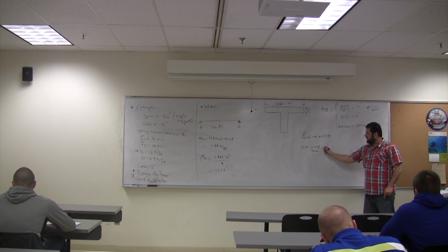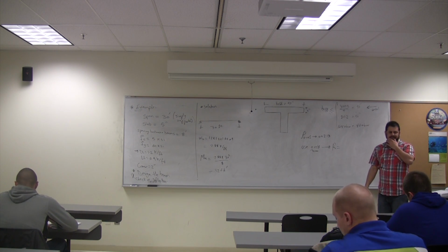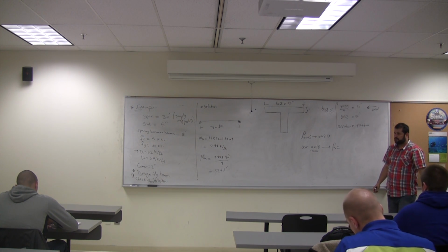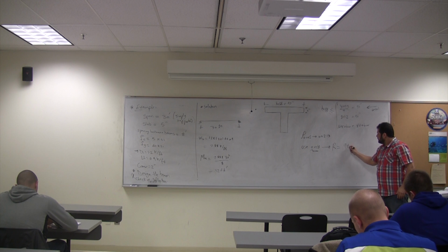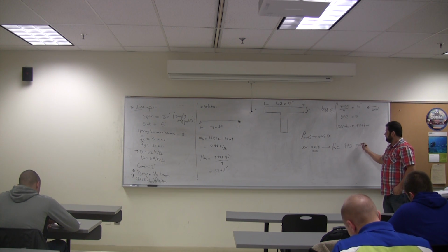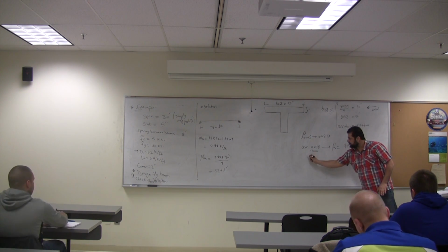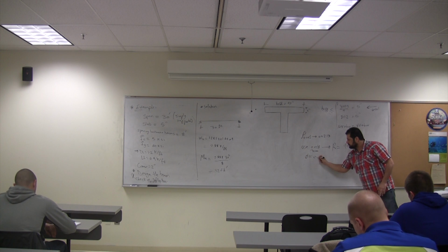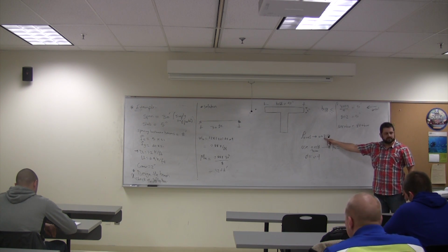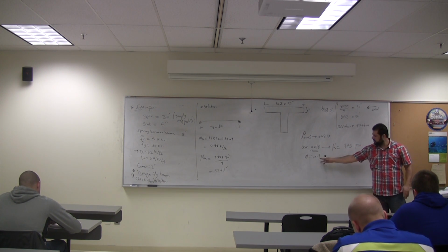If I use that, what's R? From the design aids. 943. It's 943 psi. This is in psi. Now here we go. Now, how much is my phi now? Glenn, you know what's my phi? It's 0.9 for sure. Because I'm using less than that. I'm using less than that. So it's for sure 0.9.